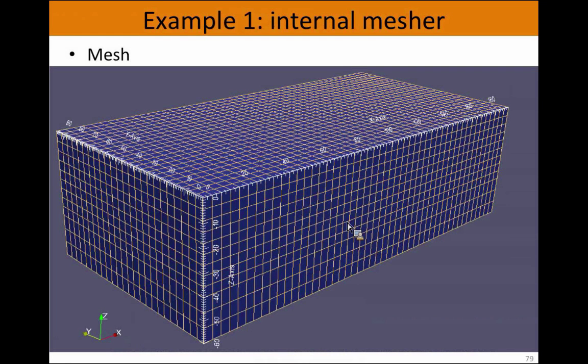So this is the layout, and this is the mesh we will generate. Pretty simple. You see the geometry, there is no variation in topography. It's flat. So the mesh is regular in the near part at the surface, and there is only one observation: it's slightly stretched at the bottom, just to gain a little bit of performance. But in general, it's not good advice, I think, to stretch the elements. The ratio 1:1 is good. But this is the mesh we'll generate.